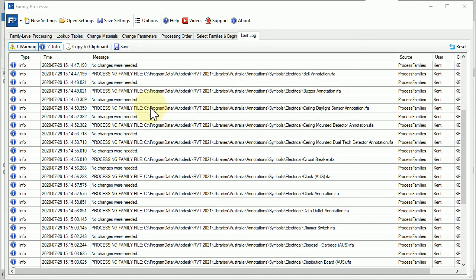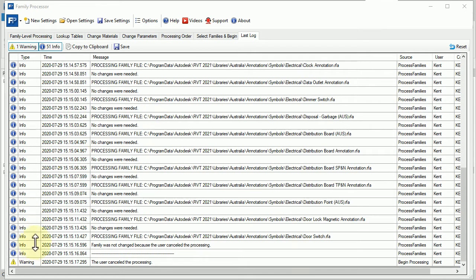All right, so when it's finished processing, you'll get a report, and at the end, I cancelled the process, but in the end, you'll get either a warning or a success. A warning would typically say that there were no shared parameters found, or there'll be a success saying that it's created the shared parameter file. You may also get a warning saying that there are duplicate shared parameter names in the same file, which you would then need to go and resolve. So that's the grabbing out all the different shared parameters.